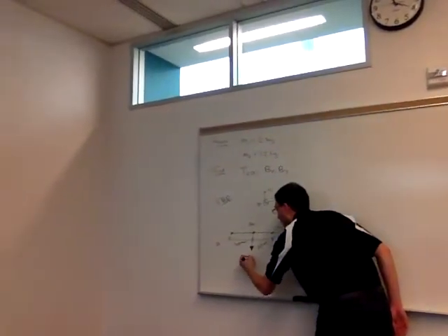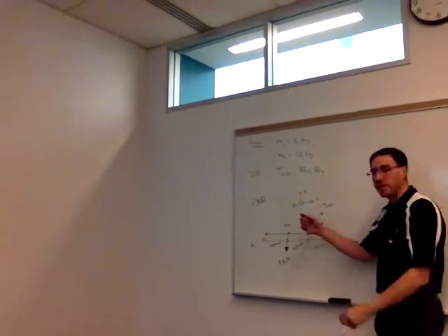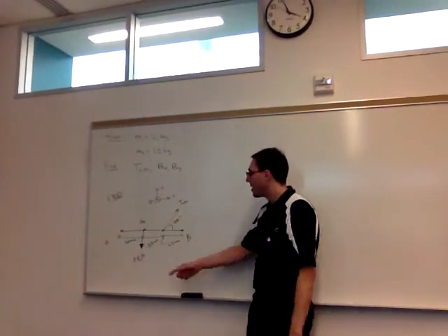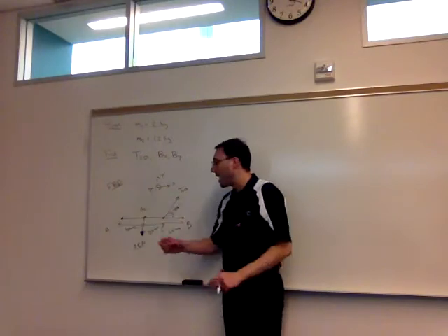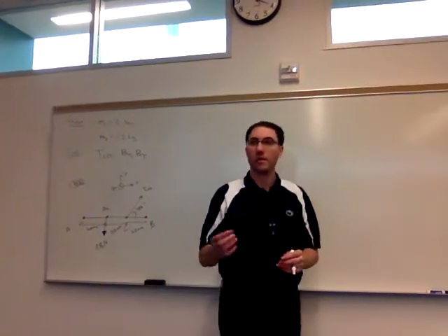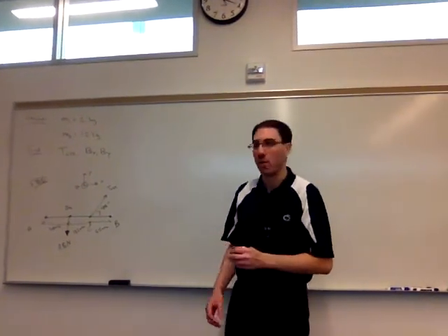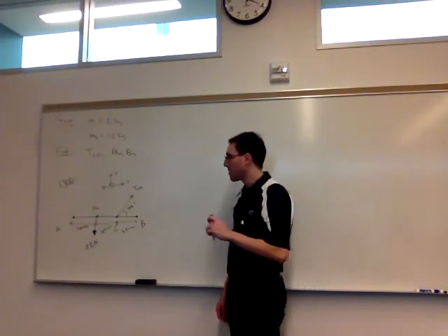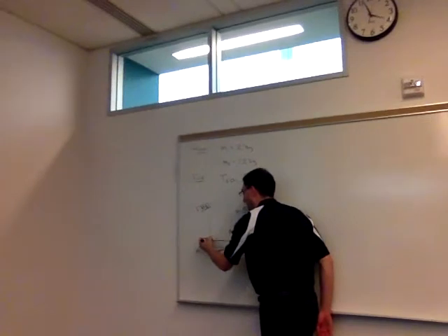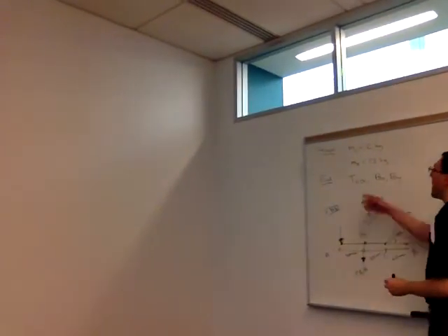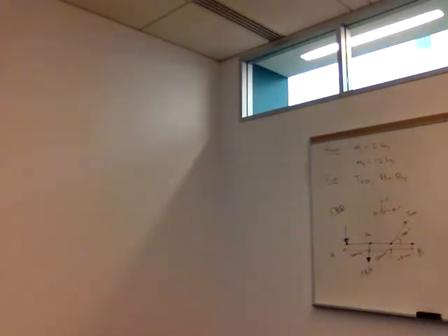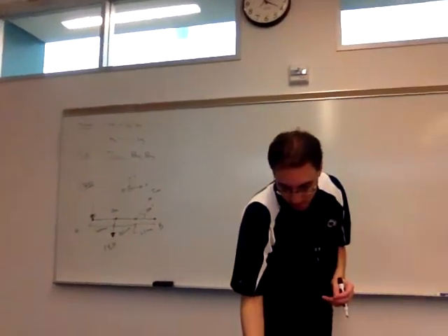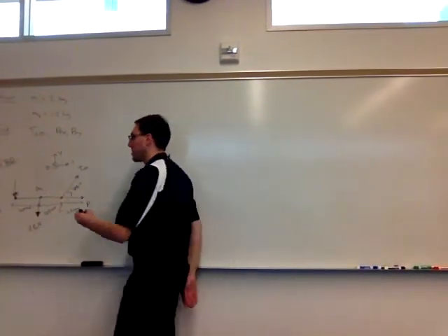Right, so again, we only want the weights of these objects. So this is the weight of the arm itself and the hand that we're going to model, because we're going to see it's not radically smaller than the object that we're holding. So what other force do we need? Right, the force of the Mountain Dew Extreme. It has a mass of 2 kilograms, so it's going to have a weight force of 19.6 newtons.